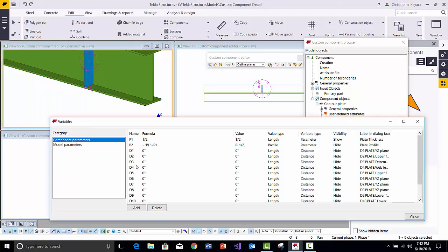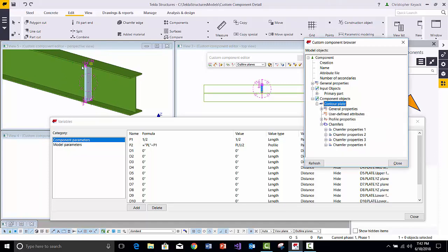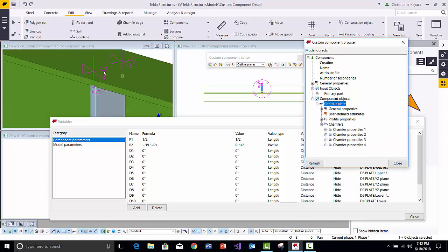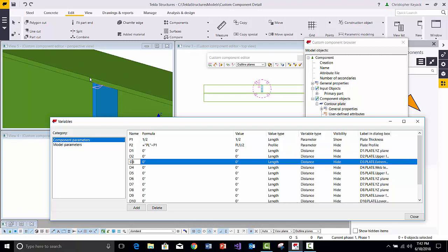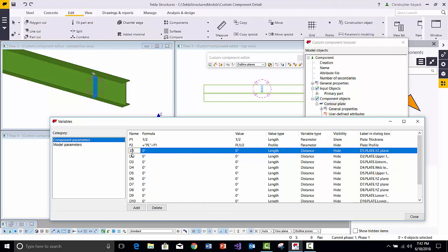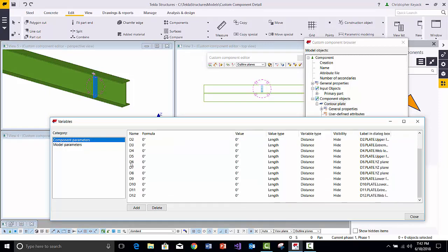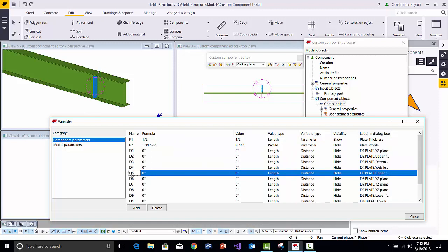Now, as a good test to make sure that you've gotten all of the points, because when you're first starting out, you kind of go, did I get all the bindings? Luckily you can graphically see them here in the model, and when you highlight them in the list, it does highlight them in the model, so you can quickly check whether you've bound a point in all directions. And a suggestion I give is to ask, does it mathematically make sense? You had 4 points and you have 12 bindings that you just did here, so it looks like you most likely got all of the points. But again, you can spot check by selecting and highlighting and then seeing where it appears in the model.